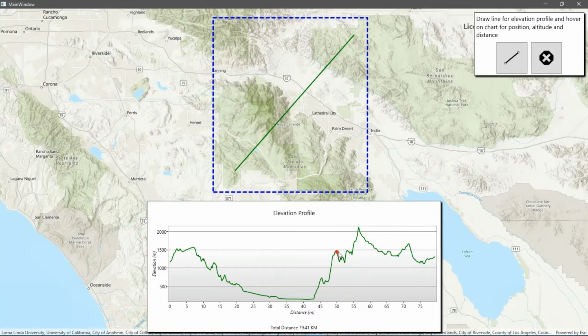Now in this case, I could be calling out to a geoprocessing service that's being run and hosted in ArcGIS Enterprise, but I'm actually just using our local server. So it's all running on my device here. The tool that's being run just produces that end result line with all of this elevation and position information in that line itself. But the app is what's generating the elevation profile. So that's not part of my GP service. That's an example of calling my geoprocessing tool, getting the result, and then doing something else with it in order to present it in a nice way to the user.